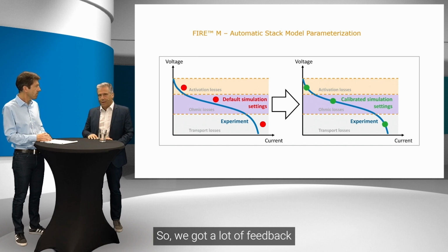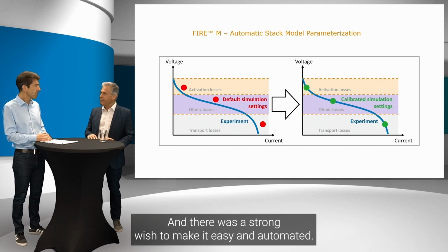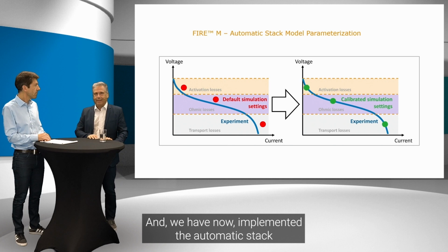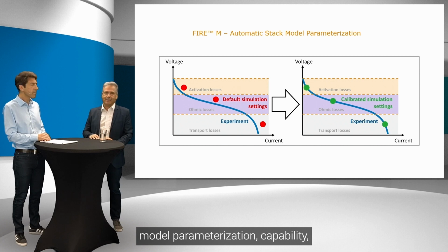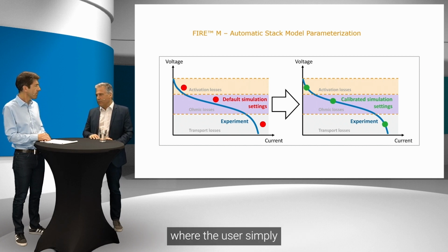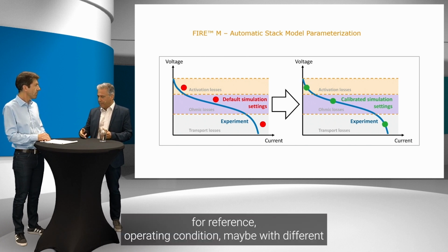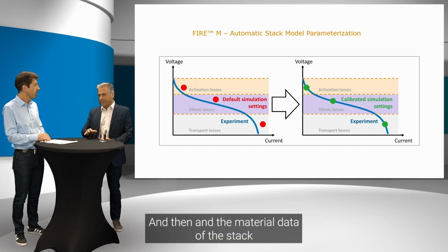So we got a lot of feedback regarding the parameterization from our customer base, and there was a strong wish to make it easy and automated to set up a working model, a reliable model, and we have now implemented the automatic stack model parameterization capability, where the user simply specifies UI curves for a reference operating condition, maybe with different temperature levels, different pressure levels, different stoichiometry, and the